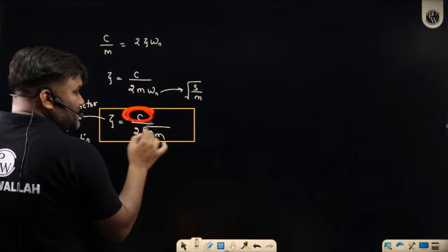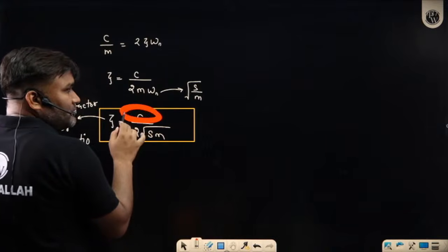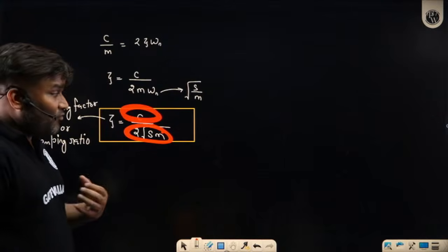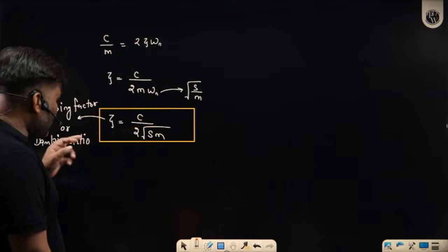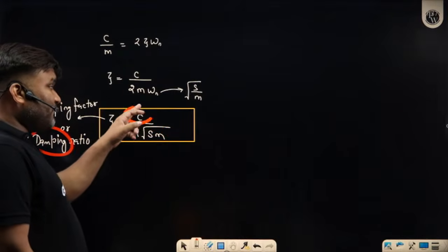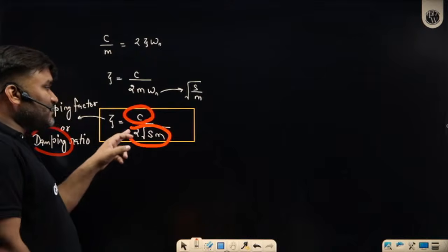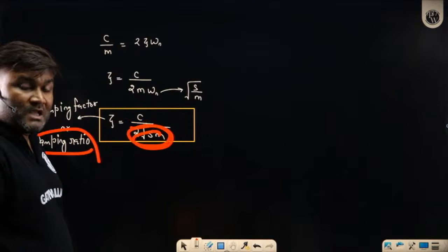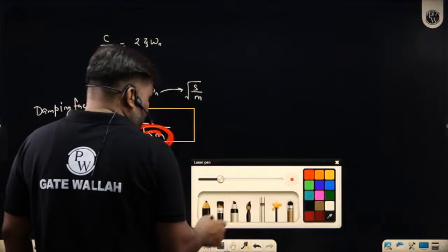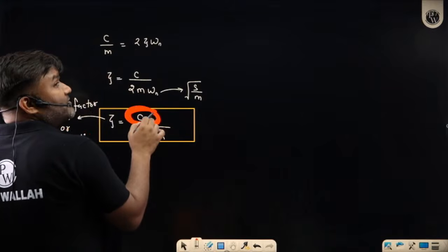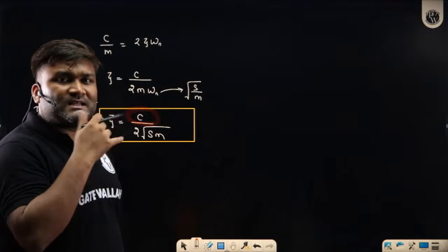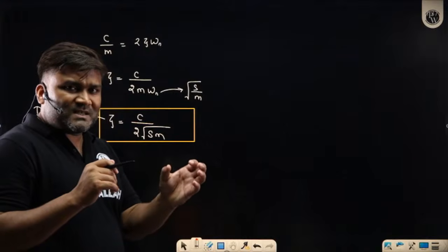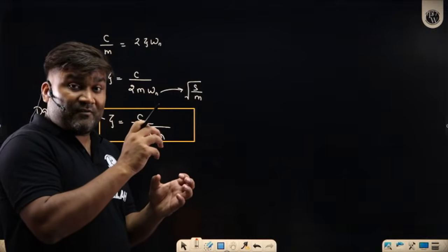So whether this energy losses term or this energy absorbing term is dominating, that ratio is called damping ratio. Whatever friction we have compared to stiffness and mass properties, this ratio is damping ratio. Now depending on which is dominating, there is nothing like high friction or low friction. These are comparative things. As compared to stiffness and masses, if we have friction dominating,